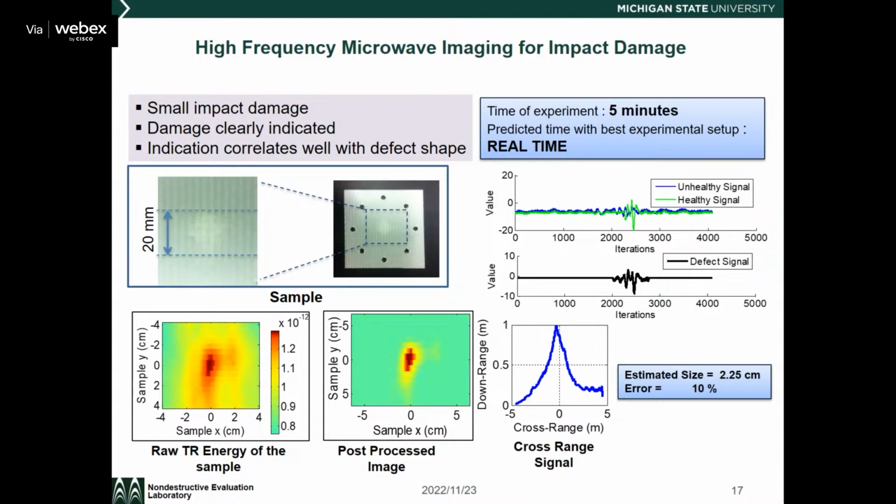In a far field, the resolution is determined by the wavelength, right? The radiation frequency. This is called Abbe's limit in physics. Abbe's limit tells you in a far field, if we don't talk about metal materials, that the resolution is determined by the radiation frequency or the wavelength. It's half wavelength resolution. For 3 gigahertz microwave, the best resolution you can achieve is 5 centimeters in free space. Of course, in materials, even worse, right?